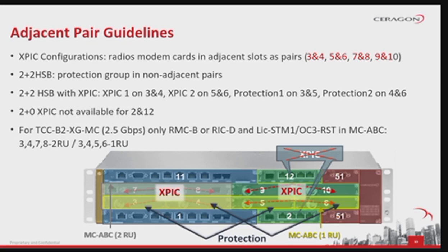For example, XPIC group number 1, slots 3 and 4. XPIC group number 2, slots 5 and 6. Protection group number 1, slots 3 and 5. Protection group number 2, slots 4 and 6. 2 plus 0 XPIC configuration is not available for RMCs in slots 2 and 12.